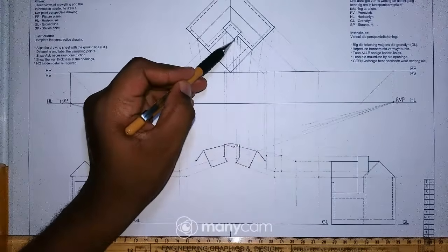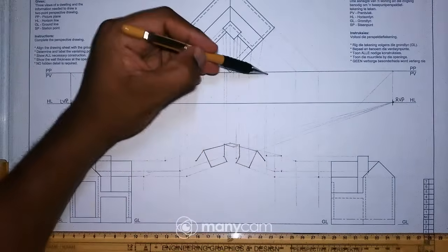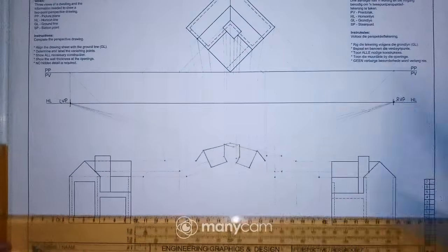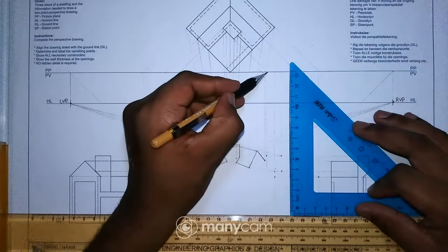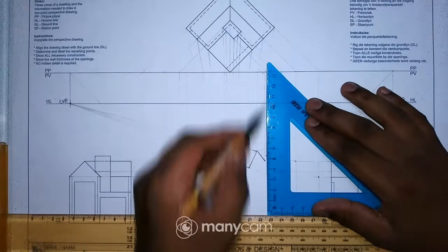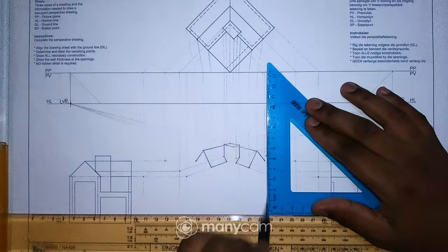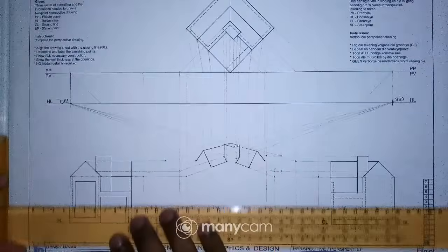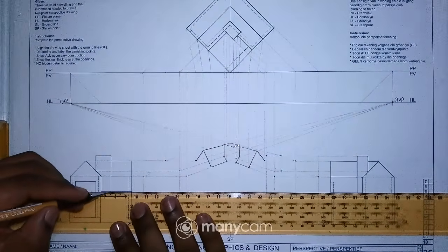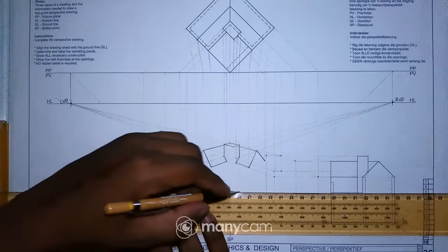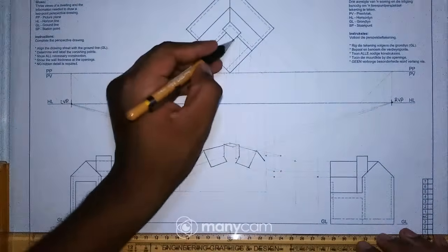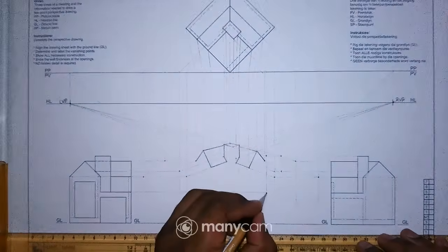So I'll have to extend that line down to the picture plane and then draw a vertical line. Okay, let me just do that. So I have a line there, a point there, and then obviously I draw a vertical line, and now I have to project the height of that point. So I'll have to take this point to that line that I've drawn now. Where is it? It's right there, right? Let me confirm. Yes, it's right there.